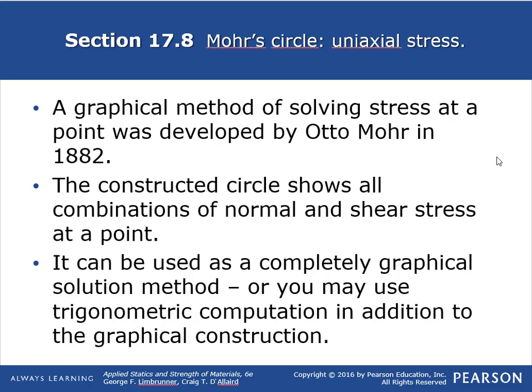Okay, in section 17.8, we're going to be talking about Mohr's circle for uniaxial stress. A graphic method of solving stress at any point was developed by Otto Mohr in 1882. He constructs a circle that shows all the combinations of normal and shear stresses at that point. It can be used as a completely graphical solution method, if you were to draw everything to perfect scale,